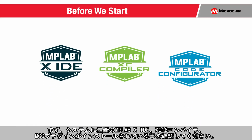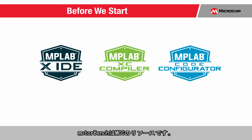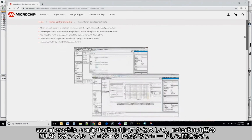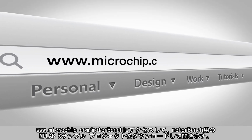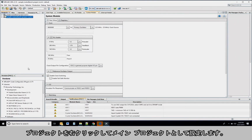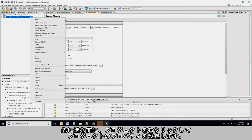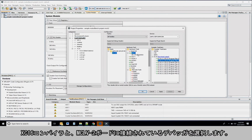Before we start, please make sure you have the latest MPLAB-X IDE, XC16 compiler, and MCC plugins installed on your system. The motorBench tool is available as a resource within the MCC. First, download and open the sample MPLAB-X project for motorBench by visiting www.microchip.com/motorbench. Right-click on the project and set this project as the main project. Before you proceed any further, right-click on the project and configure the project properties. Select the XC16 compiler and the debugger connected to your MCLV2 board.